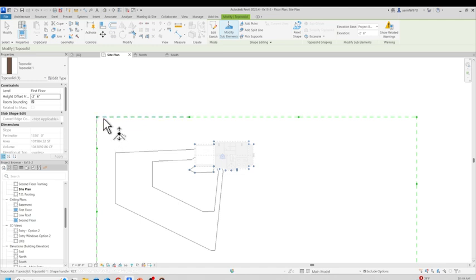I'm going to decrease right here, make this -3 feet 6 inches. So I'm going to click right here and make it -3 feet space 6 inches. While I'm there, let's go ahead and highlight it, and there are many different ways you can copy and paste. You can copy to the clipboard, so I'm going to push the control button, Control C, and then come over here and click on it, Control V, paste it back in here.